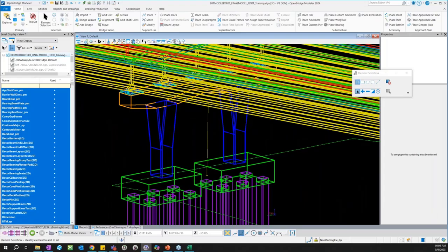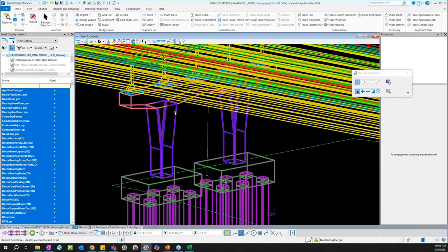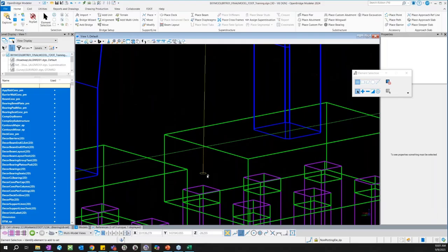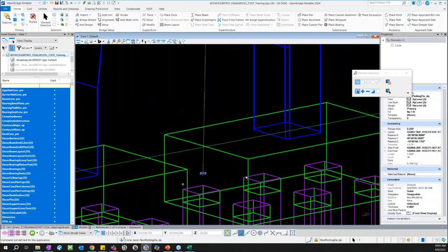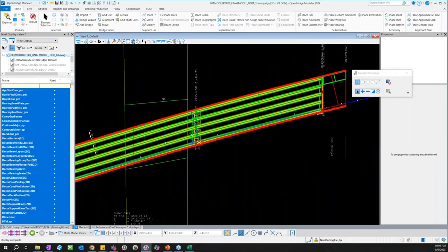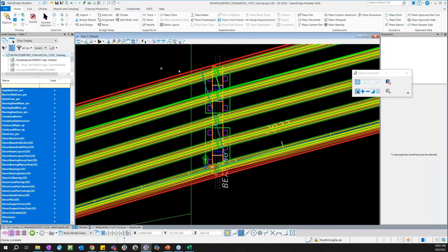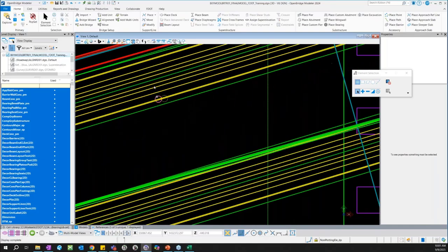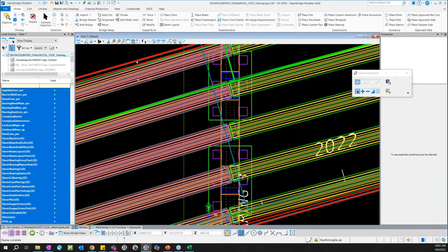So now that we have this straight line distance, similar to what you would do in clash detection, you can use, again, the top and bottom to compare those 2 points. Let me see. So now we can use the cross section tool. We can get the stations for these points. We can use a cross section, or I guess we'll use section call out, so it's like an actual drawing, and we can snap to these points, use that cross section tool, and then we can measure there.